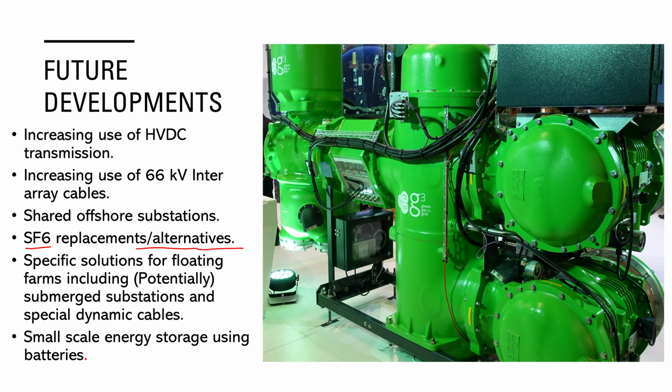Small scale energy storage, however, is for more local reasons of control and maintenance, and that is definitely going to get bigger. In addition, we may see things like synthetic inertia systems needed, because with the shutting down of large rotating mass fossil fuel plants, we don't get the inertia in the frequency stability range that we need. So synthetic inertia relying on some sort of stored energy is also going to be a thing that happens in the future.